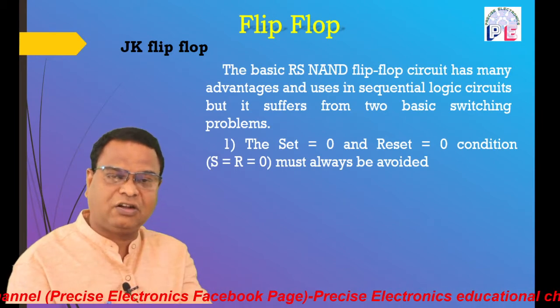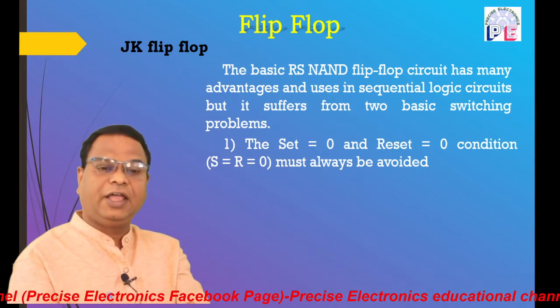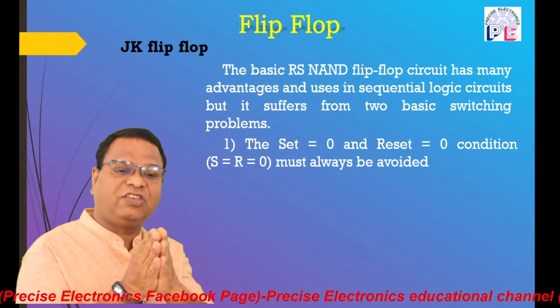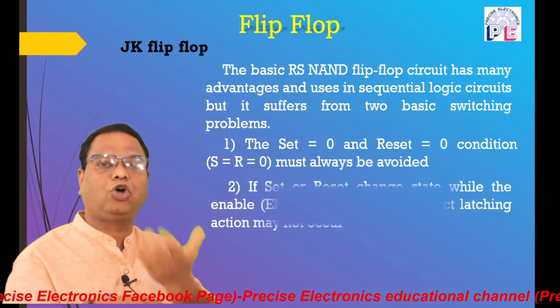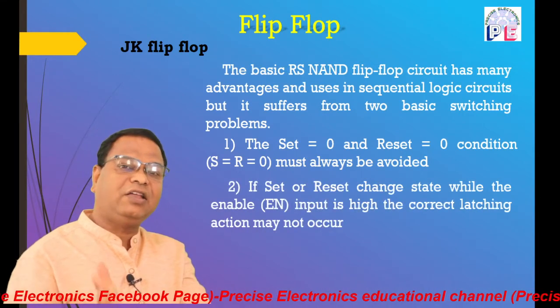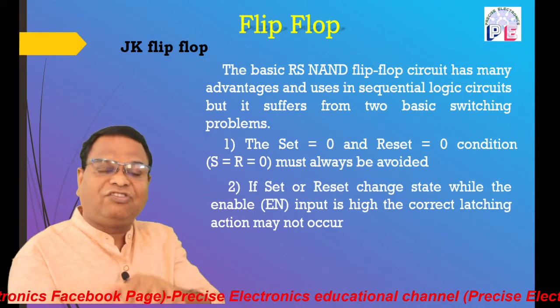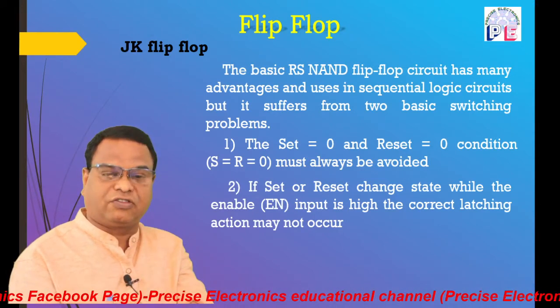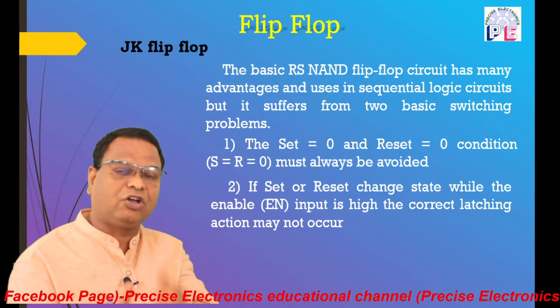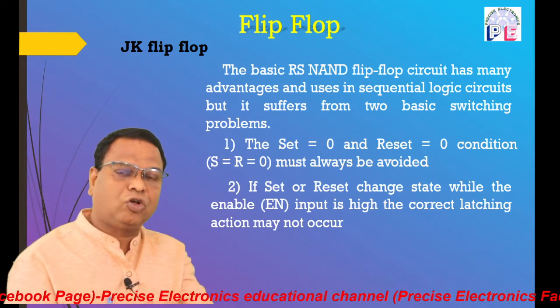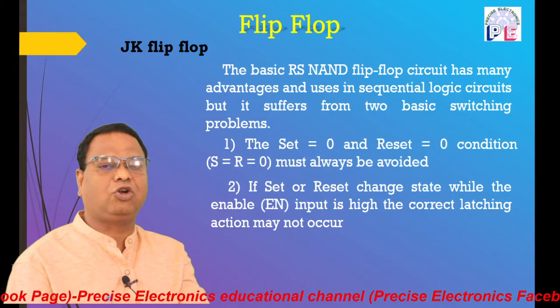The second drawback is that each set or reset changes the state, that is from high to low or low to high, while the enable input is high. So the correct latching may not occur, which means the transition of proper state may not occur.